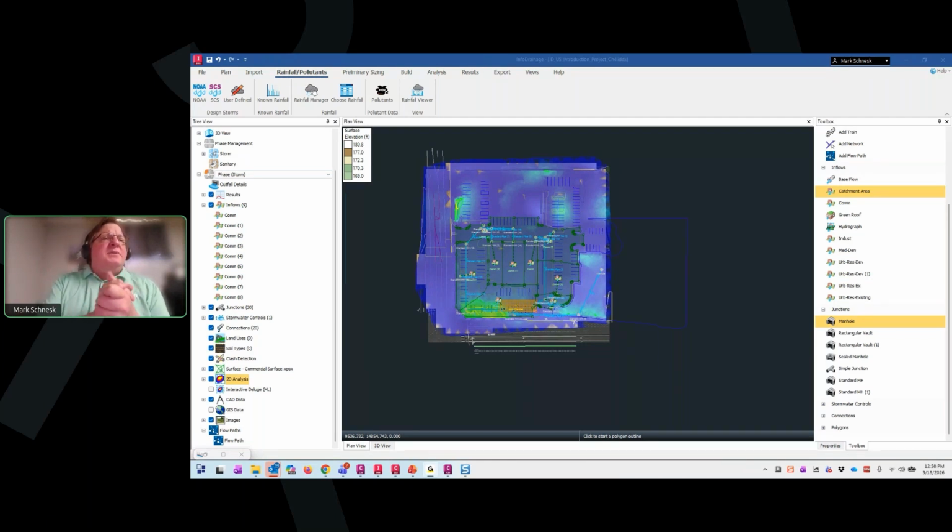Mitch says we have instances where we put erosion control logs on slopes to keep flow in sheet flow. Can it model something like that? I'd imagine you could create a custom channel to do that. When you create your channels, you can do a custom cross section, and I bet you can model something like that, or even make a surface out of it. I imagine it could. Oh, you're using it to act as a velocity trap type of thing to keep it down. I will find out about that.